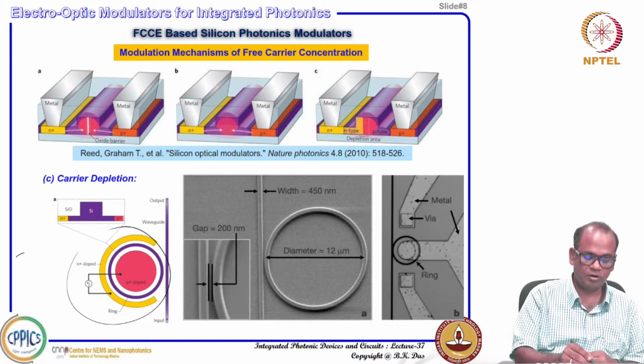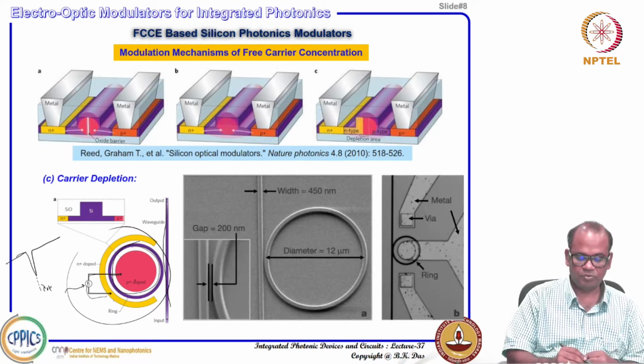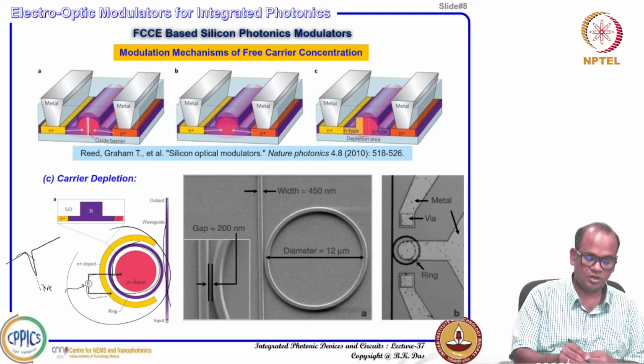If your ring resonator has a resonance notch like this, you can use an operating wavelength lambda OP, and then if you tune, you can change the refractive index. You can change the phase of the ring. This is your ring waveguide, this is your bus waveguide, this is P-type doping, and this is N-type doping, and you are giving a signal here. You can give a reverse bias, then your data here. After the reverse bias and data, you can modulate here.